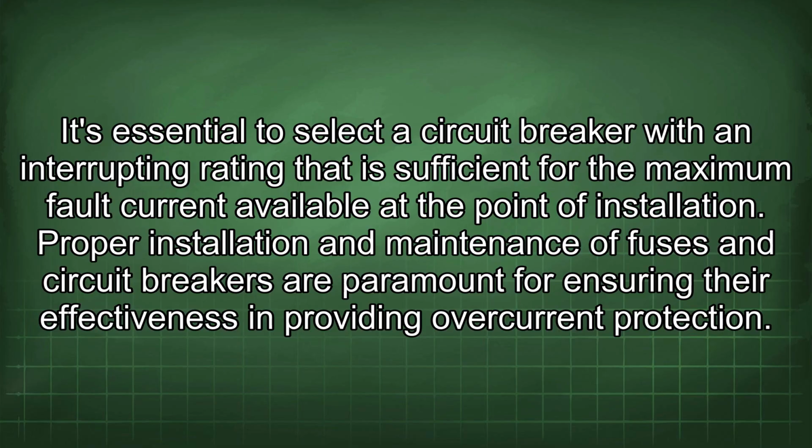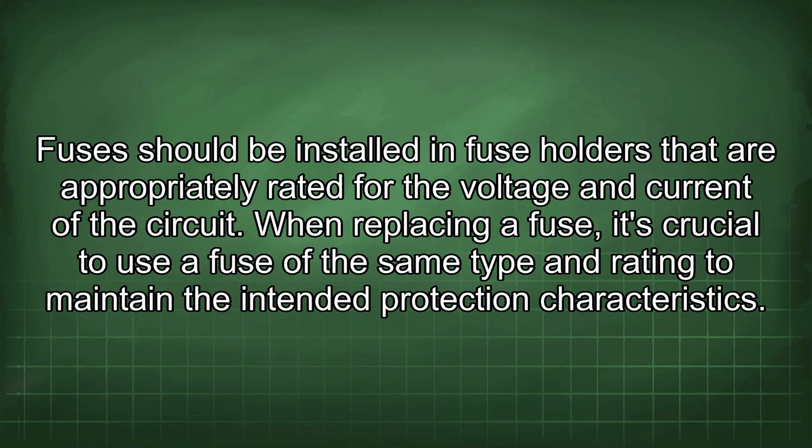Proper installation and maintenance of fuses and circuit breakers are paramount for ensuring their effectiveness in providing overcurrent protection. Fuses should be installed in fuse holders that are appropriately rated for the voltage and current of the circuit. When replacing a fuse, it's crucial to use a fuse of the same type and rating to maintain the intended protection characteristics.